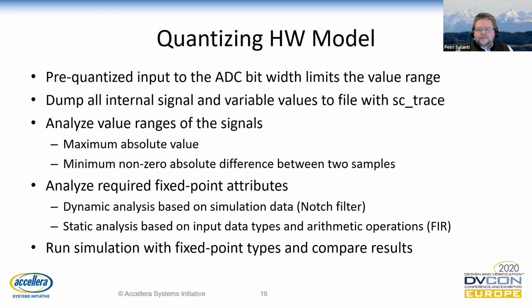The FIR filter can be analyzed statically based on the input and output data types and the maximum possible value of the accumulator with the given coefficients. The data type definitions were collected into one header file. Now it is possible to switch the data types of the digital domain between floating point and fixed point and compare the results.